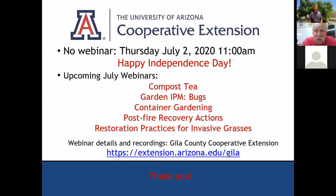That's a great question. There are three types of modules out there: the monocrystalline, polycrystalline, and the thin films. The thin films are the cheapest to get into, but they aren't as durable and rugged as the polycrystalline modules, and those are the ones you're going to see on the market. They're rated for a 25-year warranty on the materials. They'll start losing power production, about a 1% decrease each year once the system is in use.